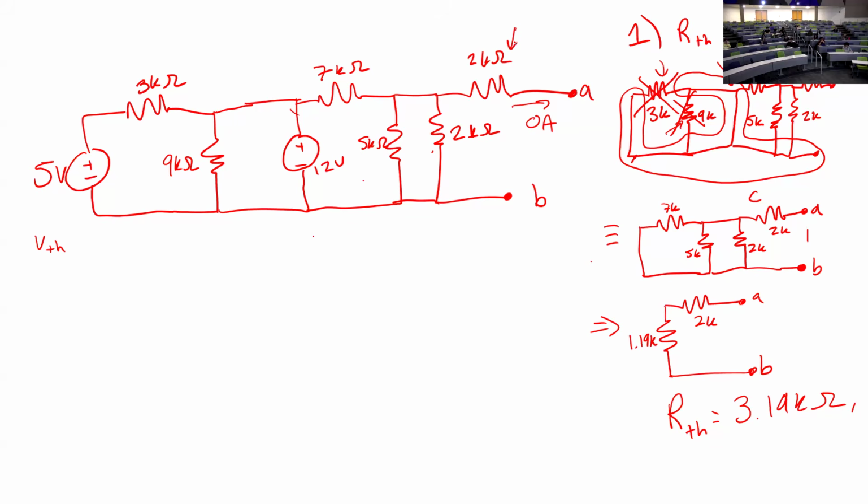Also 0 volts, right? So if I ever see this little floating type of resistor here that isn't connected to anything but A or B, I can actually redraw it here and consider this A, only for solving for voltage here. Because if I have plus and minus 0 volts across this, my voltage here is the same as my voltage here. Okay, so we essentially just ignore this one in full. All right. Any questions on that? Okay. So now when we're solving for Thevenin, I'm going to redraw my circuit.